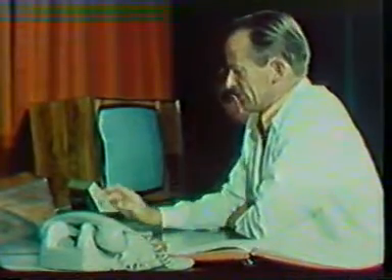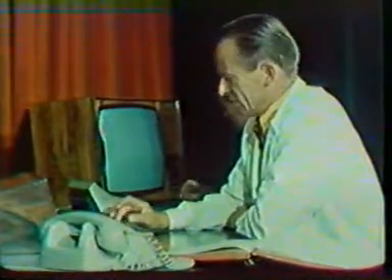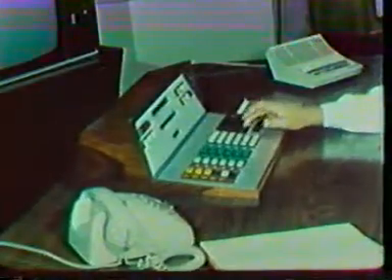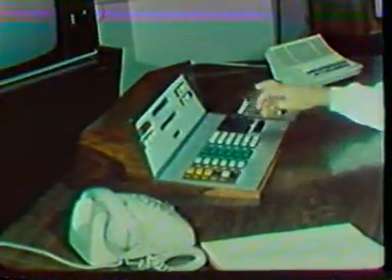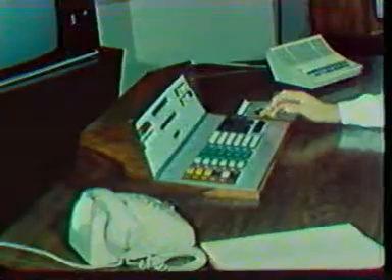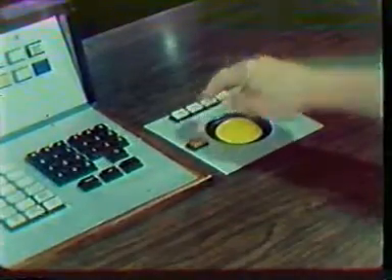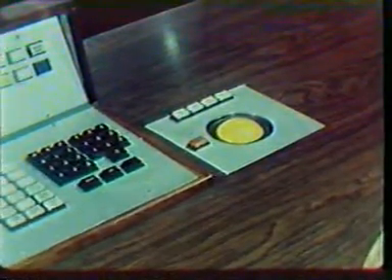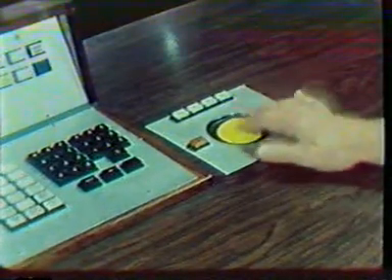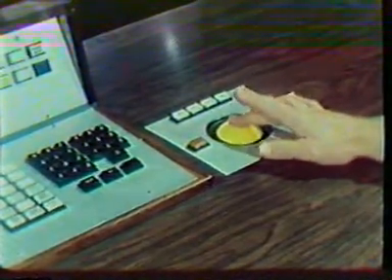For the display of plant information, the operator has at his disposal 3 color CRTs. The operator's console consists of function push buttons and alphanumeric displays built up from light-emitting diodes. For direct addressing on the CRT, a tracker ball moves a square mark on the screen. The 3 console windows display process variables and are also used for addressing and changing of parameters.